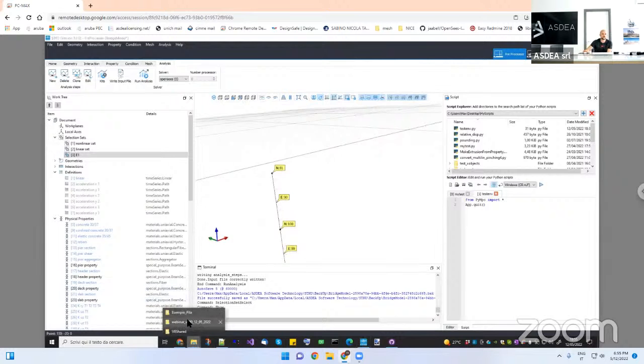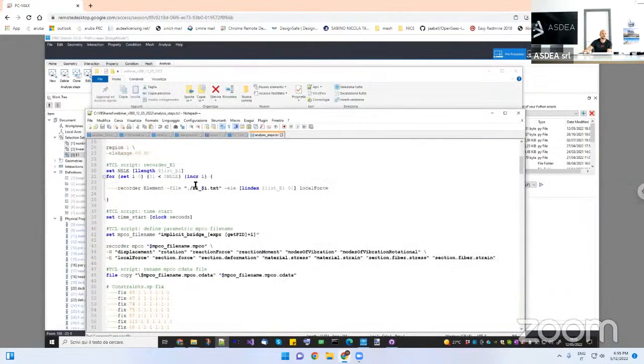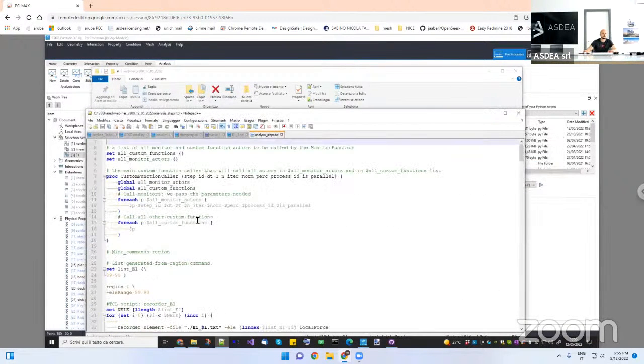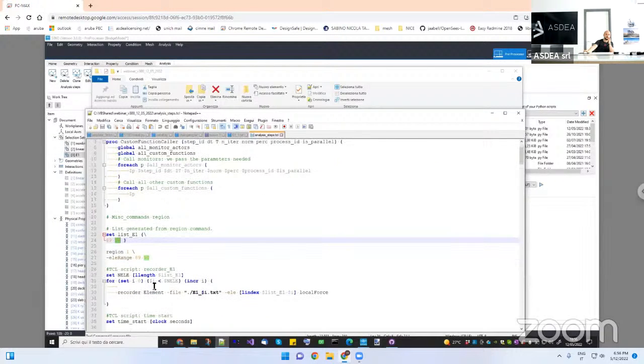So in my OpenSees TCL script, what I should have now is, let me find the recorder element, it should be at the very beginning. Okay, list E1 is 89, 90. So it is following the direction of the element, right? Basically what I do here is that for E equal to this one, I loop in every one of these lists and I create a file. So E10 will be the first one, E11 can be the other.